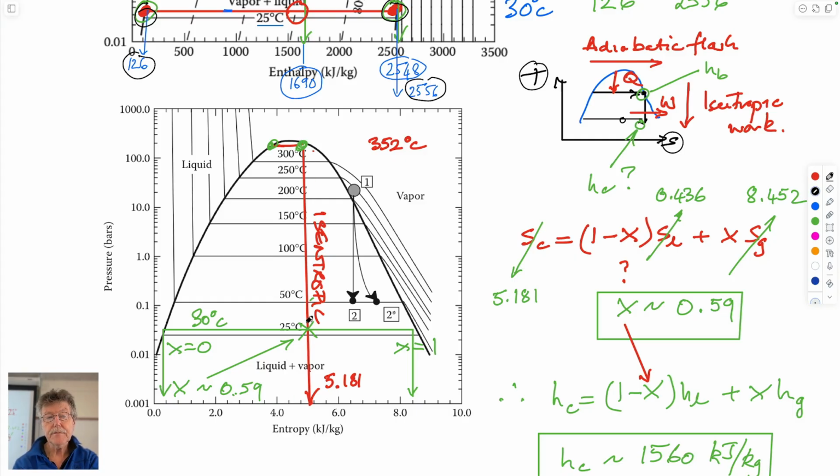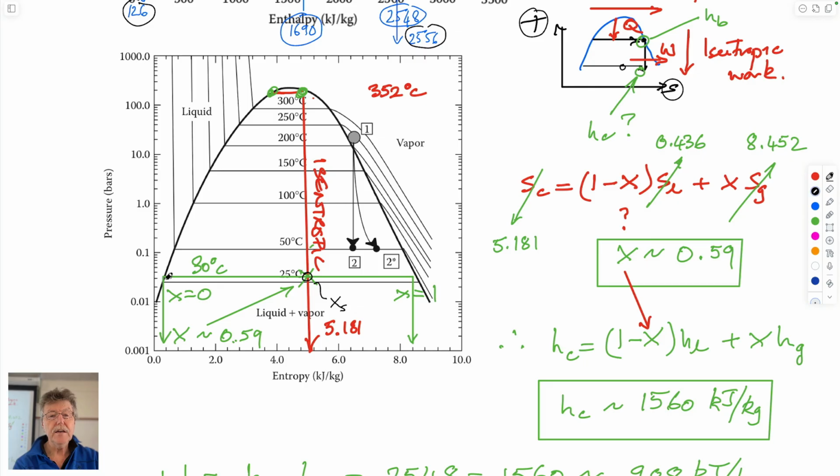And in doing that, it will end up at this point. And we'd like to know exactly what the value of the steam content is that represents this point. We could do it by realizing that this is 100% steam and this is 0% steam, and just dividing this up to 10%, 20%, 30%, 40%, 50%, 60%, 70%, 80%, 90%, 100%, which isn't bad. This would be just less than 60%.